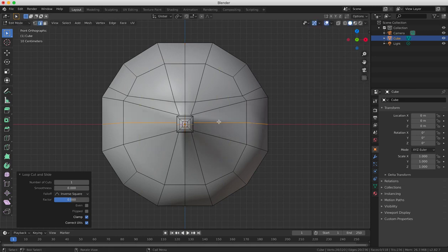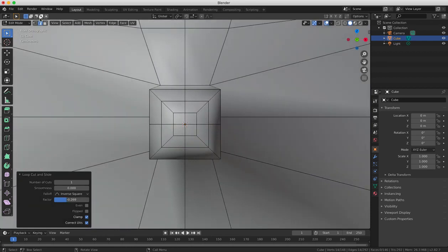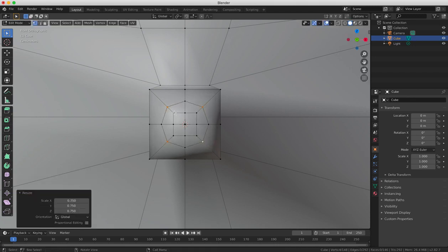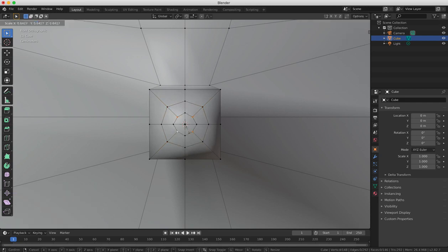The more faces you have, the easier it is to model your object, although it does increase the complexity of the object, but it gives you more control over the shape. Adjust the nose edges to make it seem rounder by selecting individual vertices in vertex selection mode, and then using S to scale and G to move the vertices until the nose looks round. Basically, you're pushing and pulling individual points and edges to try and sculpt the object to what you want it to look like.